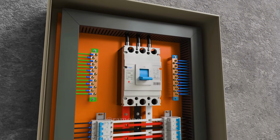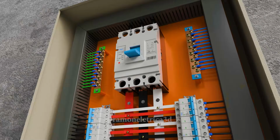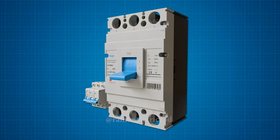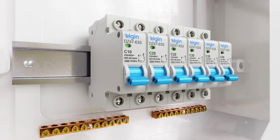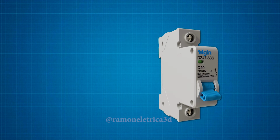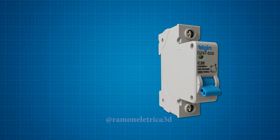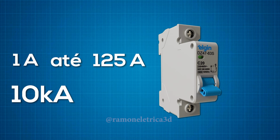Many people have questions about MCCBs, mainly about the difference between an MCCB and an MCB, and in which situations an MCB or an MCCB should be used. Miniature circuit breakers, MCBs, are the most common in residential and commercial installations and typically have rated currents from 1 ampere up to 125 amps, with short circuit breaking capacities of up to 10 kiloamps, 10,000 amperes.